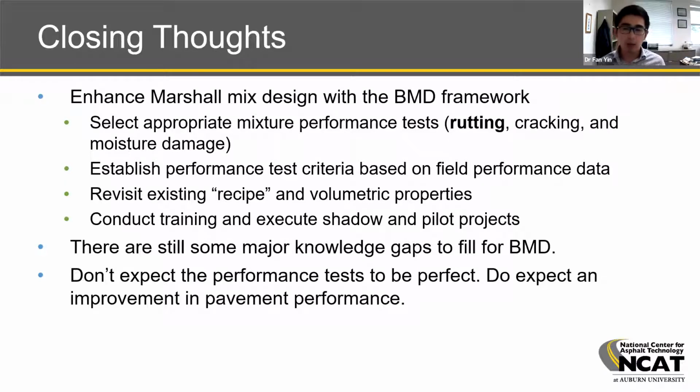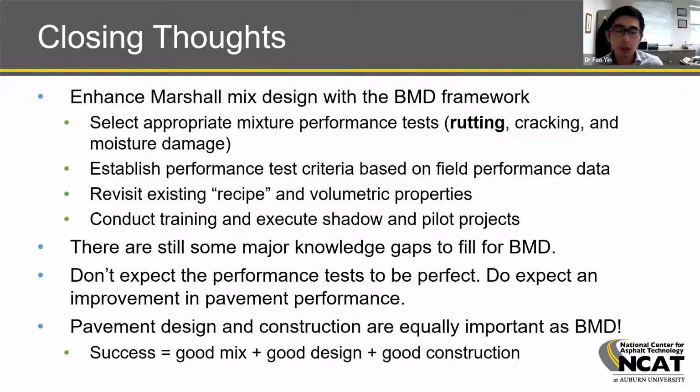Do not expect those performance tests to be perfect, but do expect improvement in pavement performance after implementing them, because they have better correlation to field performance than just looking at the VMA and the VBE. In addition to mix design, pavement design and construction are equally important.